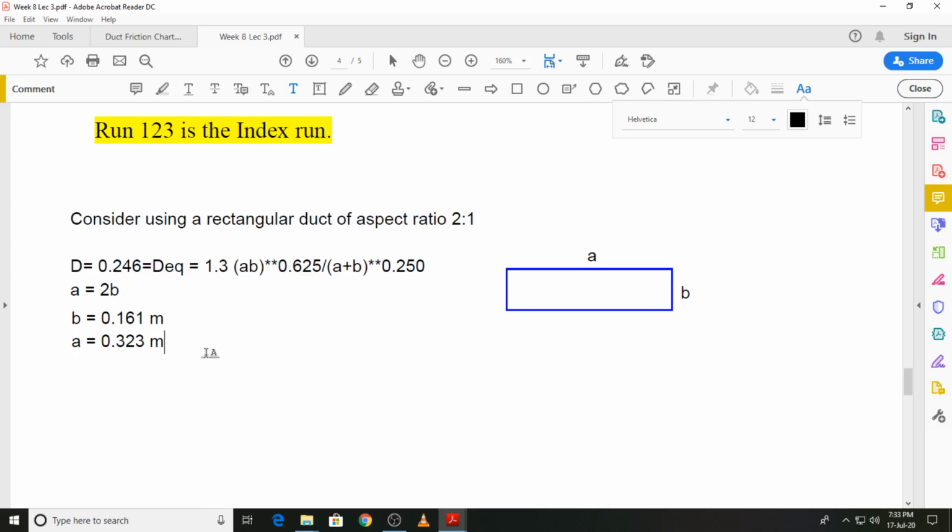And you can see now this duct will fit into that restricted space that we have, because that upper limit was 0.2 meters, and now we have a height of 0.16 meters, and that will solve our problem. Remember what I had mentioned earlier, that if we replace a circular duct with a rectangular duct, we will end up with a higher cross-sectional area, and we will also end up with a larger surface area, and that can also be verified for comparison purposes.